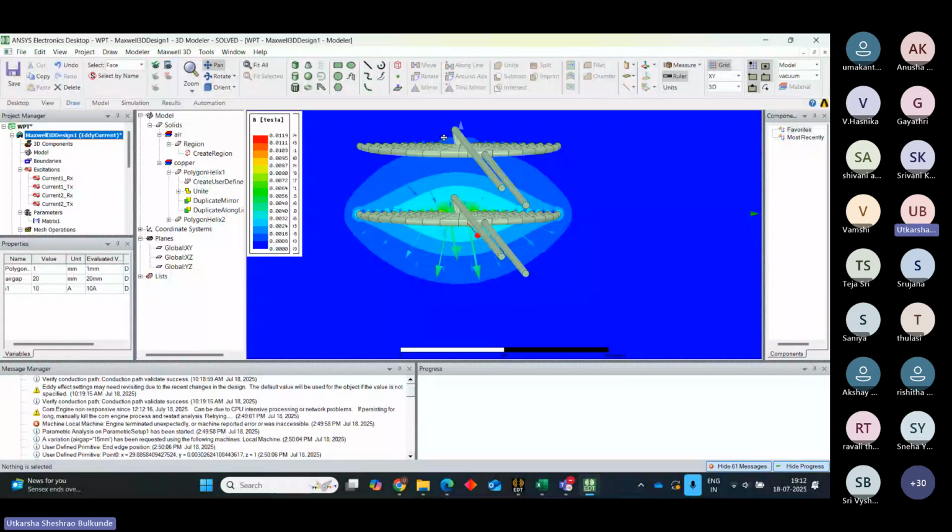After doing this also, to prevent EMI issues in wireless power transfer, a shielding is provided, meaning an aluminum plate is placed beneath your ferrite plate so that the EMI issue is avoided.